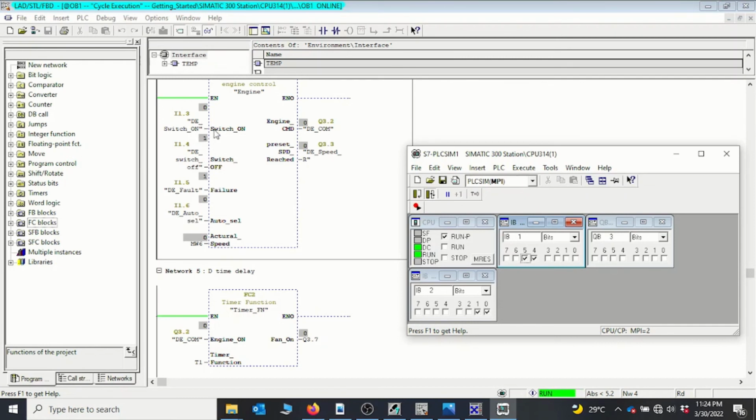And then I can now look at the on signal, which is at 1.3. So if I tick 1.3 and I untick, I can see that my engine is on, it's at logic 1 now. The timer is also on at logic 1. So you can see that it's the same function, but we've been able to call it 2 times and then use it. It's at logic 1.